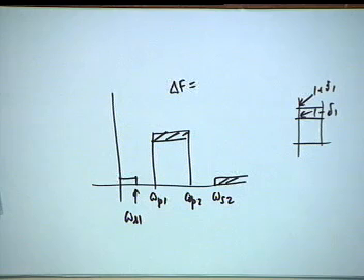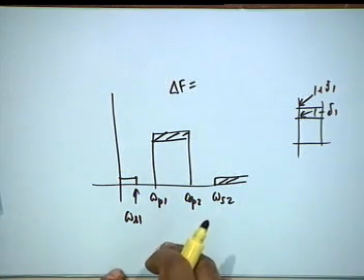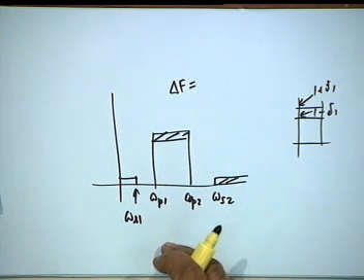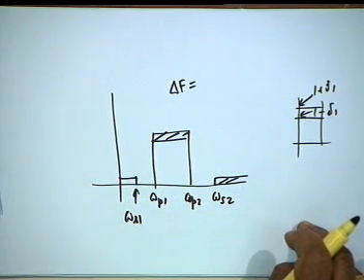In the case of a band stop filter, you shall have to exercise the same caution. In the case of a band stop filter, delta f would be omega s1 minus omega p1 divided by 2 pi, which has to be adjusted to be equal to omega p2 minus omega s2 divided by 2 pi. Agreed? I am not writing these words of caution in black and white. I hope you would be able to do this when confronted with a situation. These are the only formulas known. There is no other way.